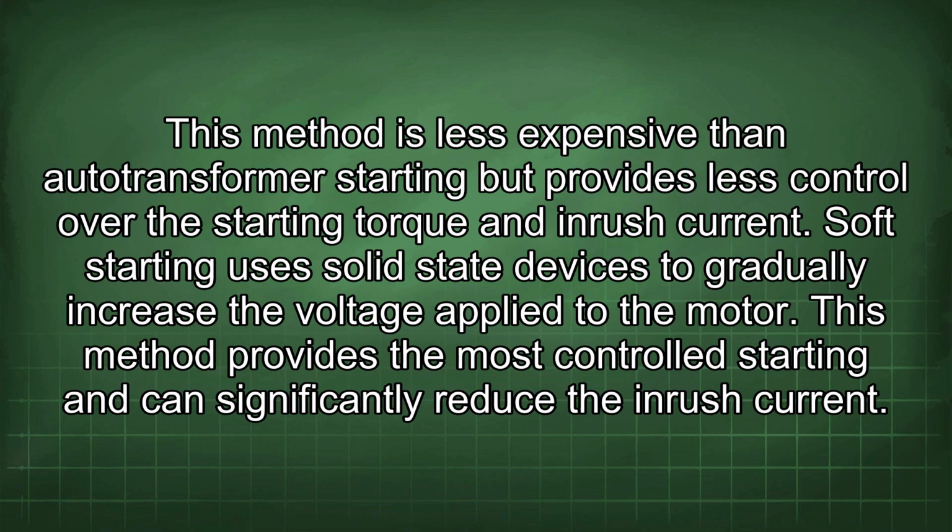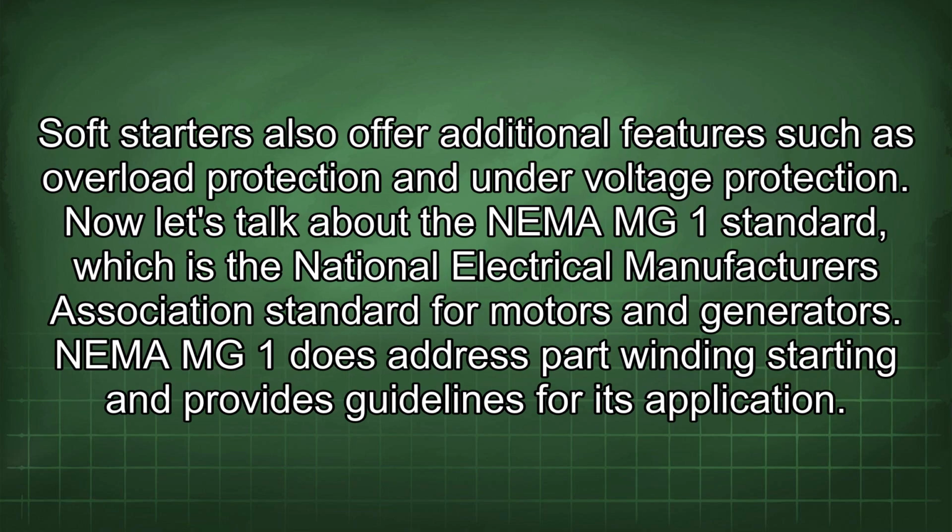Soft starting uses solid-state devices to gradually increase the voltage applied to the motor. This method provides the most controlled starting and can significantly reduce the inrush current. Soft starters also offer additional features such as overload protection and undervoltage protection.